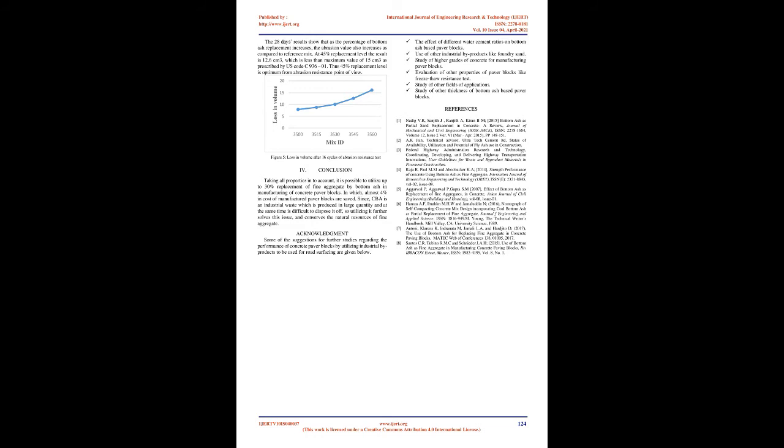The results of flexural strength of paver blocks with and without CBA are discussed as under with varying ages of 7 days, 28 days, and 56 days. From the above results it is seen that the flexural strength of paver blocks with age increases for all CBA replacements. The flexural strength at 7 days is found to be 85 to 95% of flexural strength at 28 days, and the flexural strength at 28 days is found to be 92 to 98% of flexural strength at 56 days.